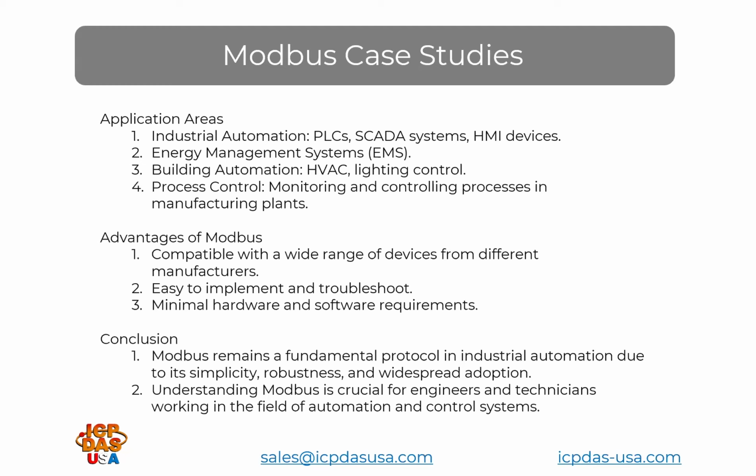There's also Modbus ASCII, which is rarely used. I think I've run into maybe 3 customers over the 10 years I've been here that actually use it. In fact, I just recently read up on it because I was very rusty on it. But essentially, you just convert the hexadecimal numbers into their ASCII equivalent. Yeah. Okay, but yeah, Modbus Plus, we don't really have any devices for.